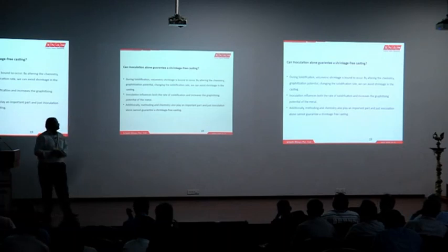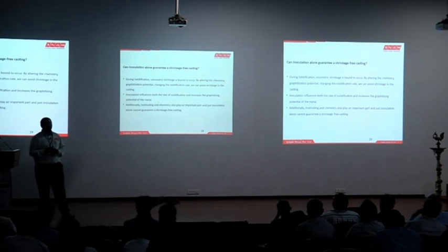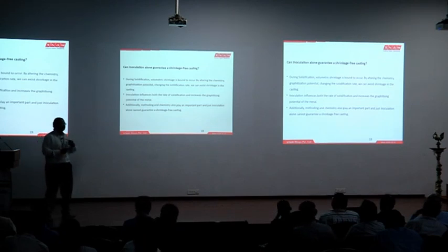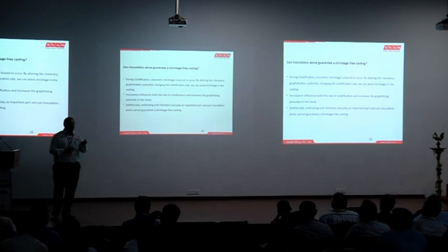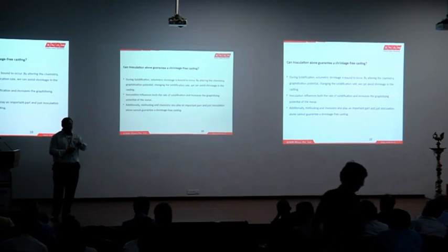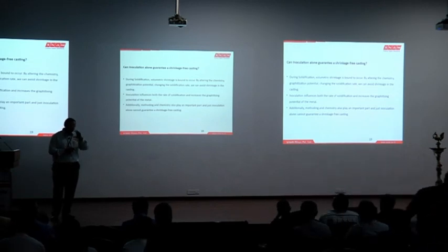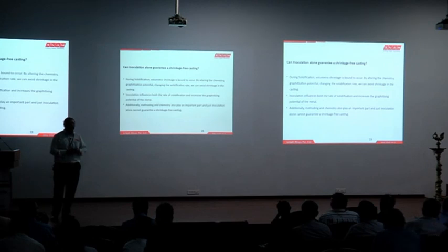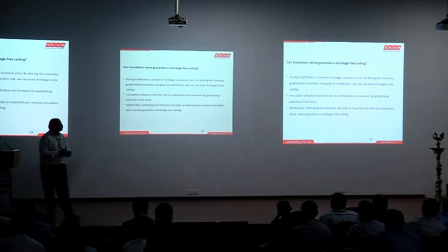Again, can inoculation alone guarantee a shrinkage-free casting? No. Actually, inoculation is just a complement, or an add-on we do. The basic characteristic of shrinkage is a solidification phenomenon. That means a void is created where your liquid metal is not potent enough to fill the entire cavity or entire shape of the component within the stipulated time at the given temperature. So when the rate of solidification is determined by your methoding and chemistry, inoculation supports it.